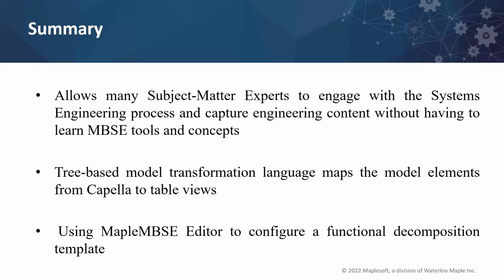Find traceability. You can also create queries to test your model quality, as you can query what are the different requirements in your whole project, and you can find information of, okay, these are the requirements that have a certain tag value, or there is a requirement that has not been linked without any outgoing or incoming relation to different model elements and so on. So basically, any kind of queries you can create with MapleMBSE, and there are also queries that you create to make it a bidirectional connection, as we saw in today's demo.